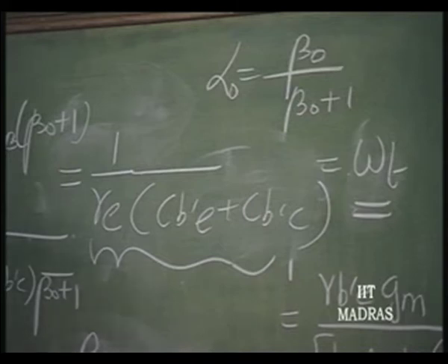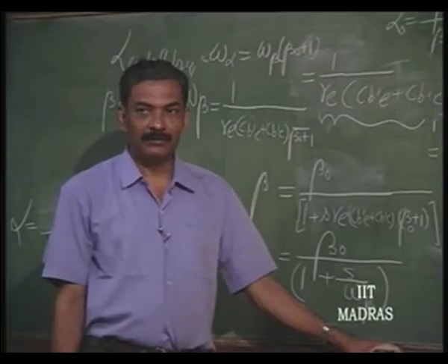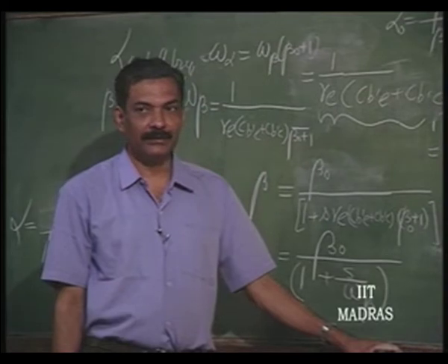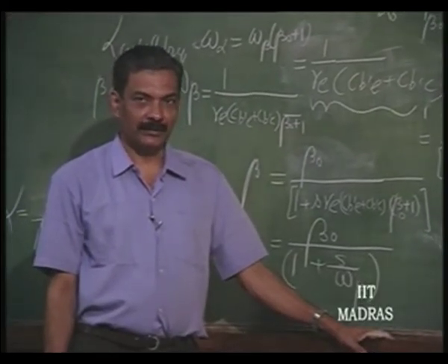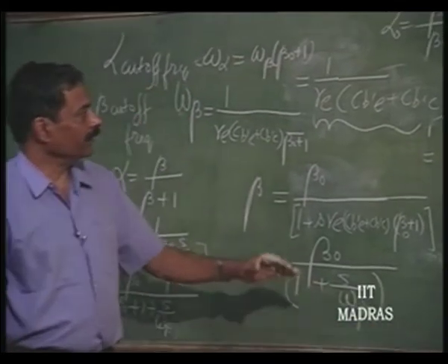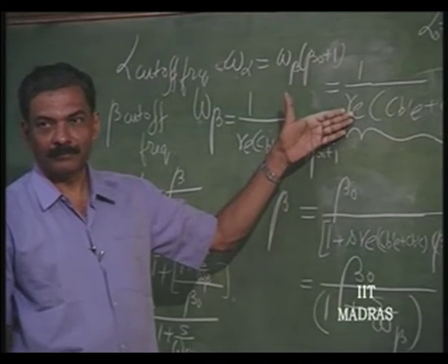So, this transition frequency f T is one of the important high frequency parameters, which is absolutely necessary to design any high frequency circuit. Really speaking, 1 over R e is Gm.